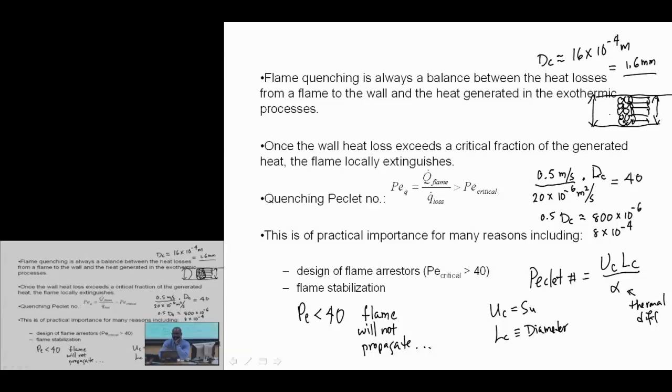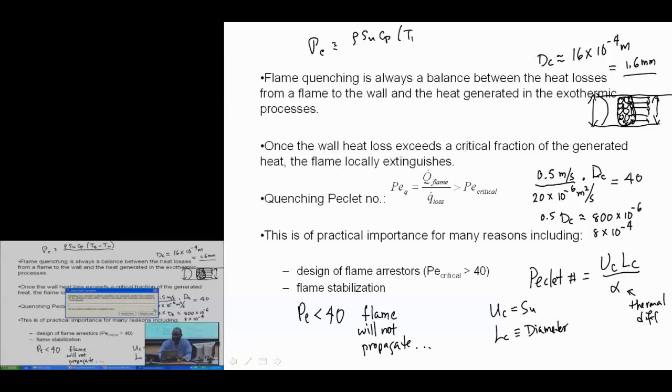And the scaling idea for this is that, well, the Peclet number. The reason why this might occur is: do I have energy in my flame relative to how much I get in terms of losses? The amount of energy that the flame carries is basically T_B minus T_wall, or T unburnt. That's my enthalpy flow in the flame. My heat loss characteristics are basically k over d, so that looks like a heat transfer coefficient, times, again, T_B minus T_U, okay?